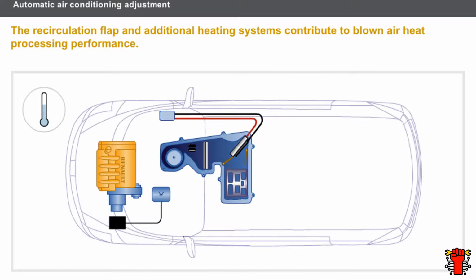When the vehicle is fitted with a thermoplunger device, the injection computer controls its activation and heating power when the engine starts. The engine temperature then rises more quickly. When the vehicle is fitted with an RCH system, the air conditioning computer controls its activation, heating power and stopping. Control of the RCH takes place when the engine starts and the conditions are fulfilled.